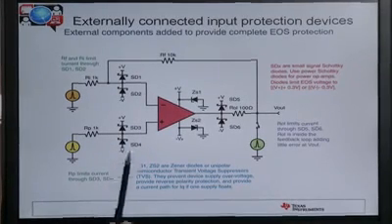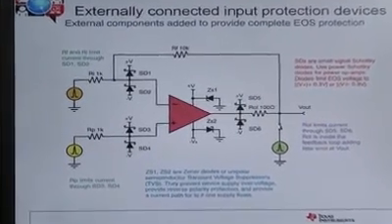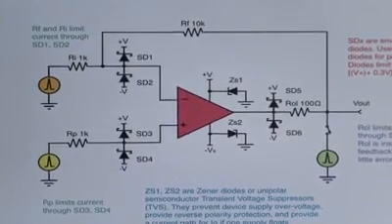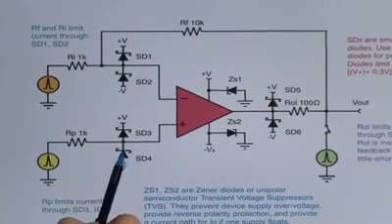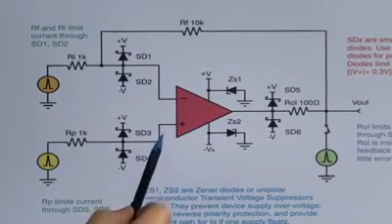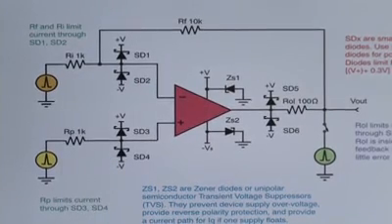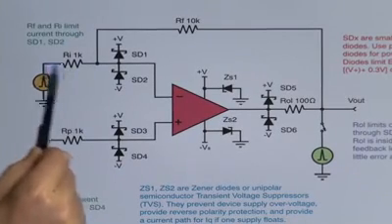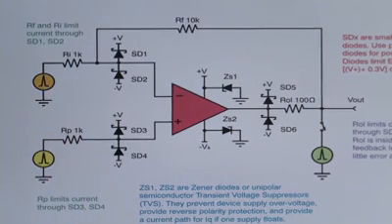Schottky diodes have a lower turn-on voltage than the internal steering diodes, but they can also be leakier and may contribute to the input bias current. A simple signal diode like a 1N4148 or something will usually turn on at a lower voltage than the internal diodes and have lower leakage current than the Schottkys. In the case of an inverting input amplifier, we've already got a series input resistor, and that provides good protection.